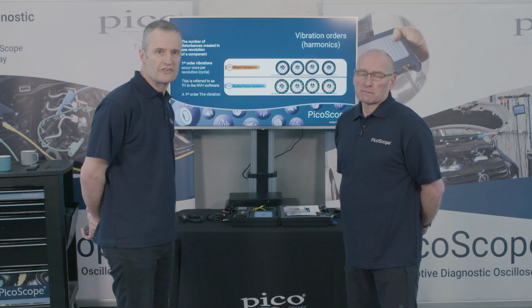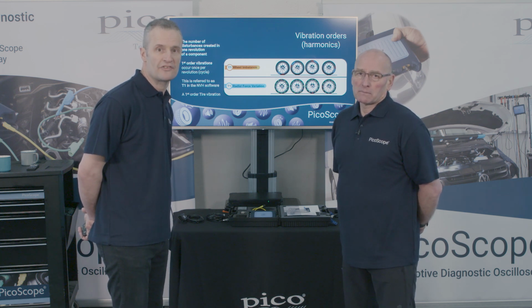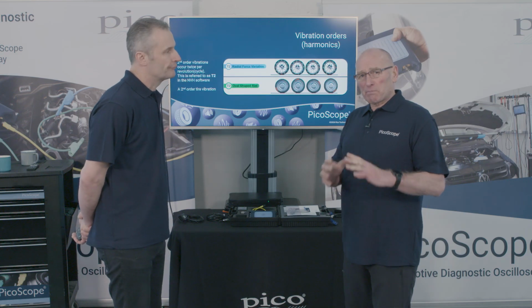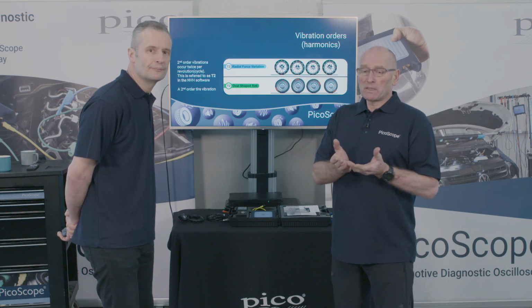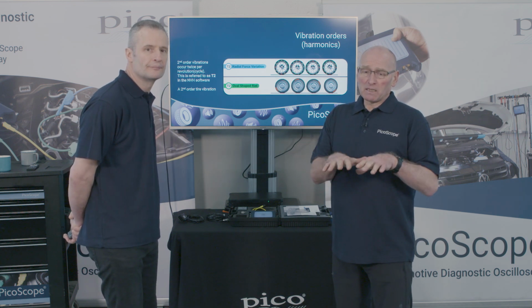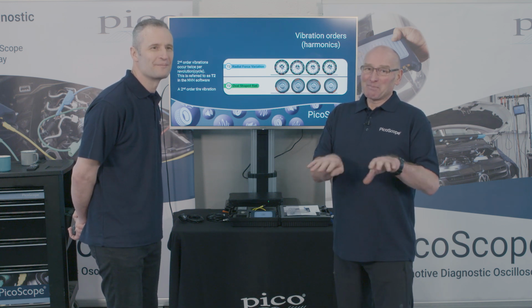about the circumference of the tyre there is a stiff spot within the tyre. So of course when that area of the tyre reaches the road surface, we momentarily get a lift off centre of the wheel hub. From a simplistic view, we always view the wheel as being round, but when it's actually got the weight of the vehicle and it's going along the road, there's a flat bit at the bottom. And that flat bit can change.